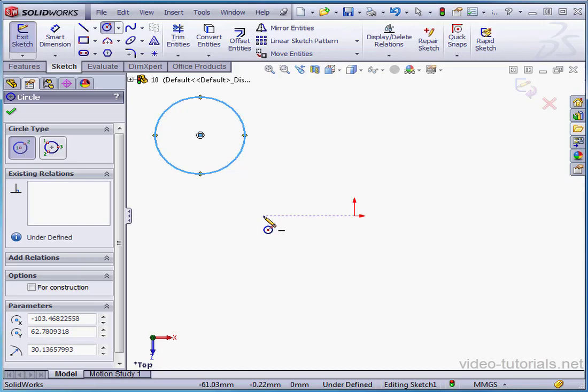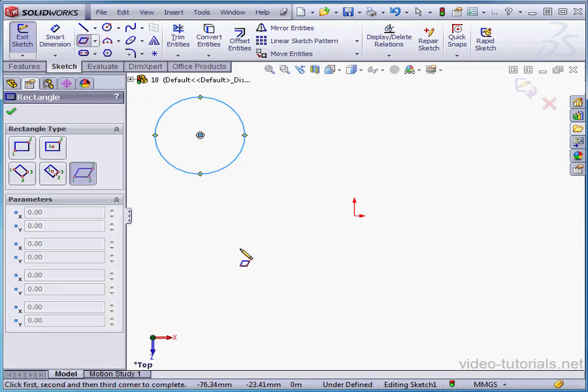Let me create a parallelogram next. Open up the Rectangle tool and select the Parallelogram subtool. I'm going to place my first point. Now the callout shows me the approximate distance and angle of my movements. My line is about 70 millimeters long at about a 30-degree angle. Let's place our second point.